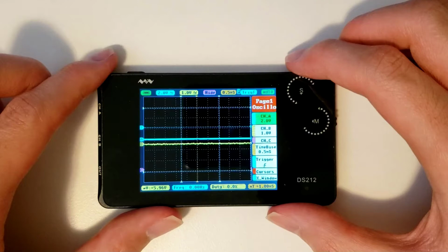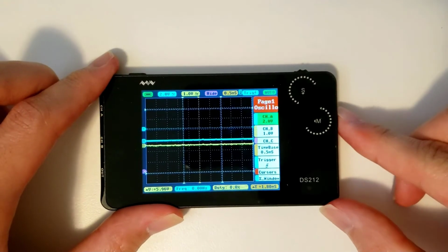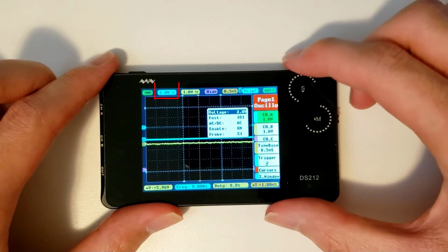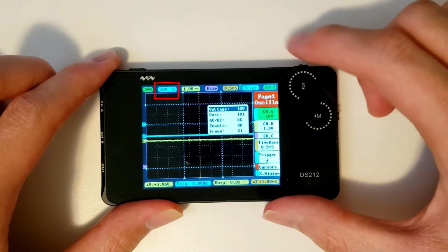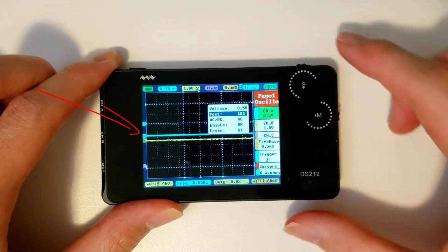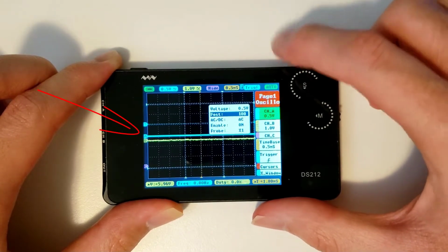The first two tabs of the list are the channel options. By entering the channel submenu by pressing the M button, you'll be able to set the parameters for the respective channel. The top of the submenu is voltage, which is the voltage division. Hover over the option and scroll the S wheel to change it. Next up is post. Change this to move the signal vertically.